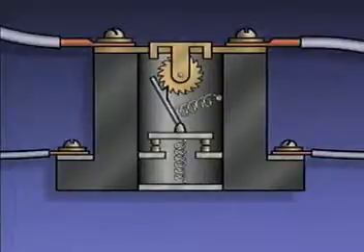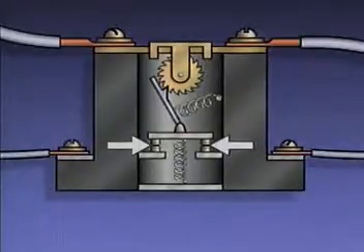While the solder is solid, it prevents the ratchet wheel and the rod from turning. As long as the ratchet wheel and the rod do not turn, the contacts remain closed and a complete circuit to the motor controller's main contactor, or M-coil, is maintained.